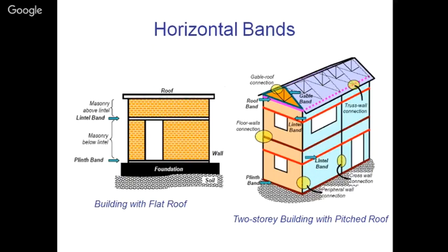So in that case, what happens? We have cracking throughout the wall, which is running from bottom to top, or we have a gable wall failure, an out of plane failure of the gable part only, which is not properly connected with the rest of the wall underneath it, and is not even having proper connection with the trusses or the perpendicular wall, as shown here.